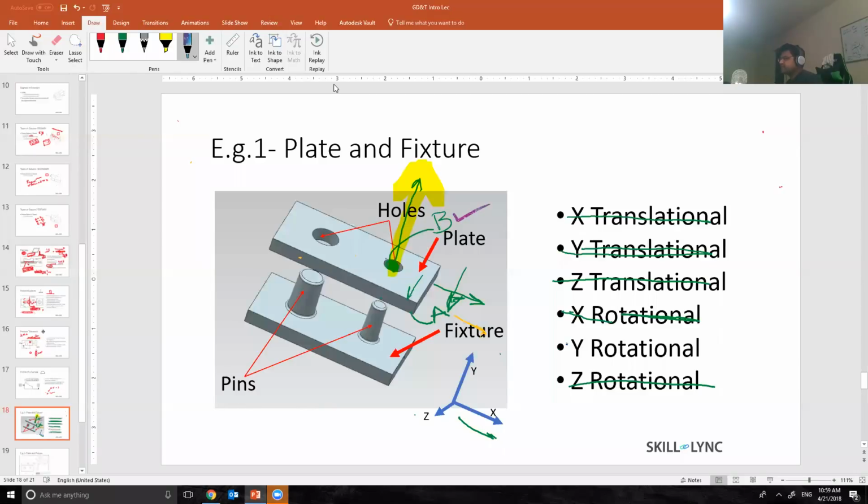How would I constrain that? So obviously the answer is simple. This would be my C datum. When I put 2 fingers in these two holes over here, the part would be completely constrained. It cannot translate along XYZ. It cannot rotate along XYZ. So this would be my C datum. That is how we constrain the part. That is how we put datums onto the surface. A datum, the primary surface that will attach to another mating part. B datum, any surface or feature that will stop 2 degrees of freedom. And C datum will constrain the last degree of freedom.